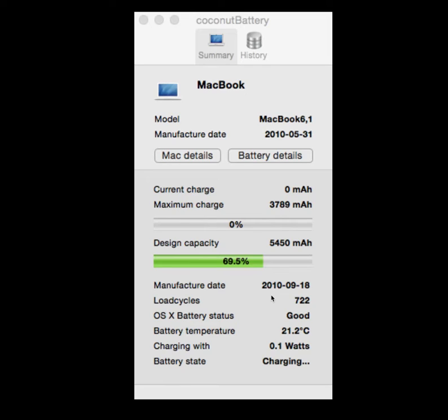One thing I would definitely say is these numbers are indicators, but you'd never know. The only way to really know what's going on with the battery is to test it, and testing means charge it up all the way, then pull the power and see if this battery proves that it's reliable. Put a day into putting the battery through a load cycle before you make an absolute determination on it, because the numbers can lie.